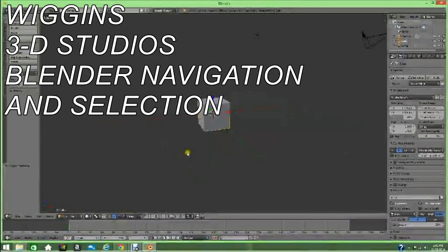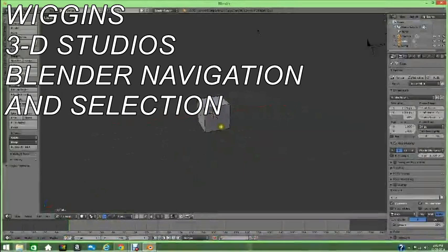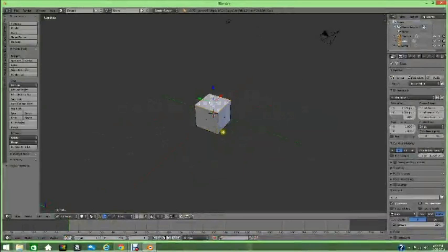Today we'll be covering the basics of modeling in edit mode for Blender. Come to your bottom tab and select edit mode. You will see that the mesh selection mode is currently on. If I type in Control Tab, it will bring up my mesh selection modes.